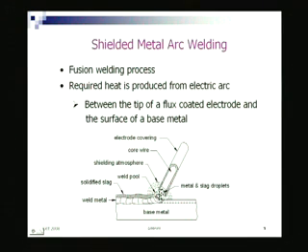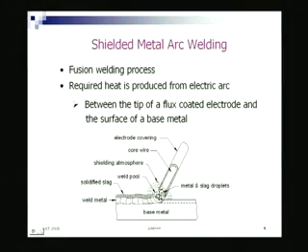Molten slag is not actually forming any gas. The flux is forming molten slag plus gas. Like you burn a piece of coal, what do you get? You get some gases as well as some ash, some residue. Here the residue is the slag and some part is the gas, right. The gas we get here is to our benefit. When a piece of coal is burned, the gas goes into the atmosphere and does not benefit us in any way, but here it benefits us, because that gas protects the arc column,